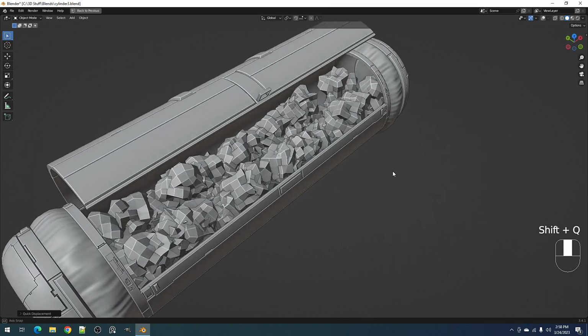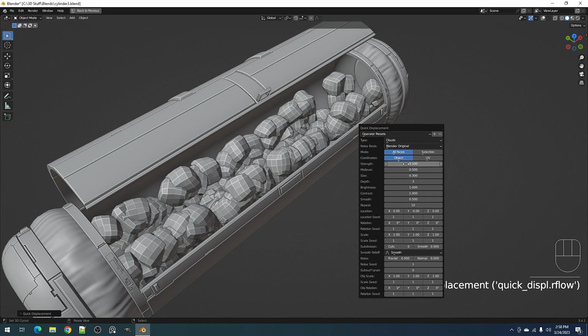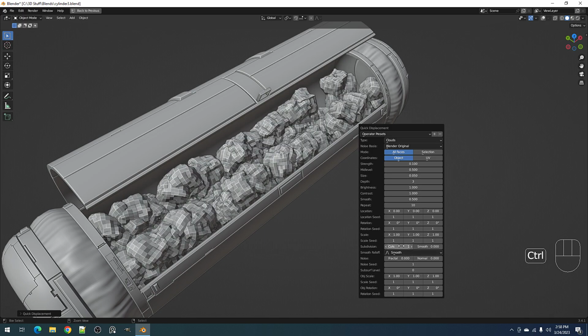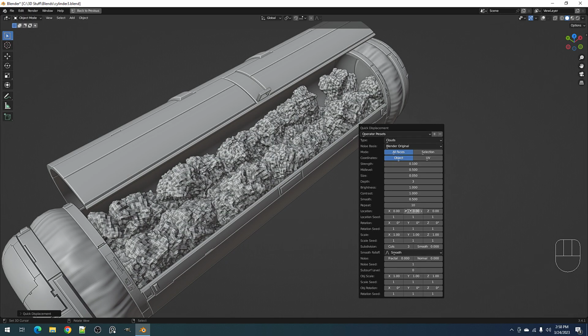Then this is the big shape, and we'll have the secondary shape. We'll have the strength of 0.1 and size of 0.05, and increase the subdivision or the cuts. This smoothing is for the source mesh after being subdivided and before being displaced.